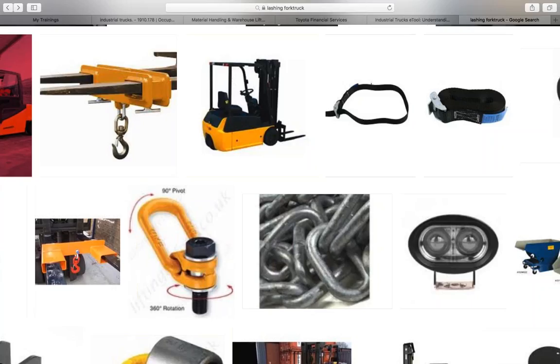Also, determine the weight of all loads before we rig them. We have to know what we're lifting, folks. It's the only way we know what the load chart should be on a crane, and also what type of rigging we're using, and to make sure that our rigging setup and our hitch are sufficient as well. I'll show you all the different hitches in just a minute, folks. I showed them to you already: vertical, basket, choker, and the bridle, and I'll show them to you again.